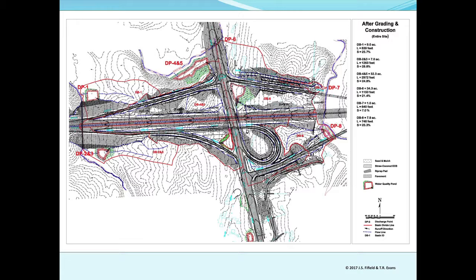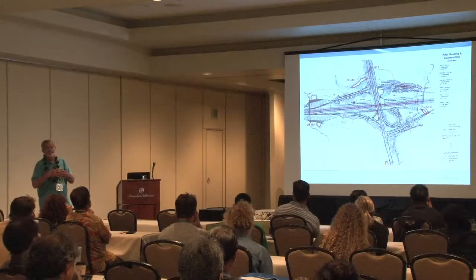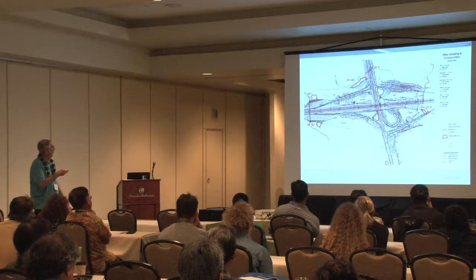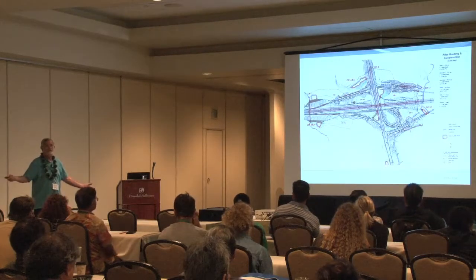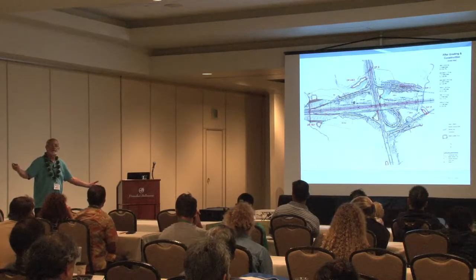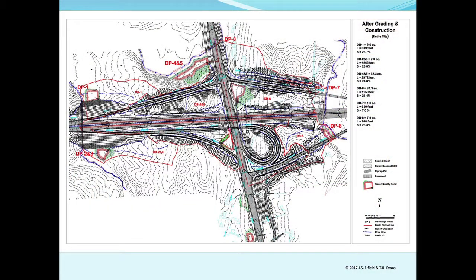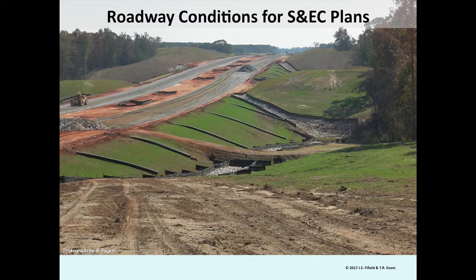Now this is one part of another class for designers, and again, I'm giving you about a 30-minute version of a 6-hour class. But over in here, these are detention ponds. If you have a detention pond, what can you do with that detention pond to help you out on a construction site? Make it into a sed pond at the beginning, not at the end. It's good planning is what it is. I mean, all of us like to see a highway project like this. It's beautiful. This is in Alabama.